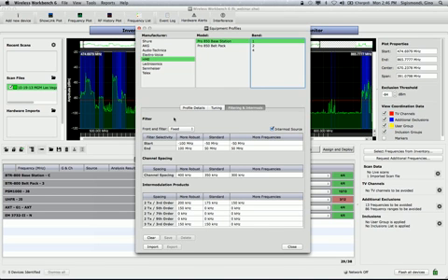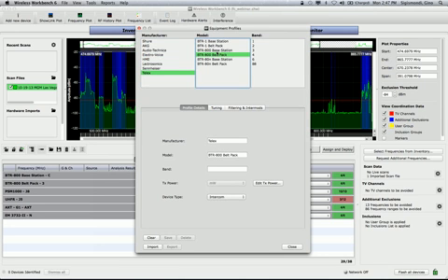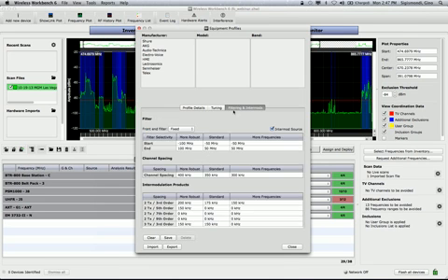And if I wanted to, I could either create a brand new one from scratch here, or I could select a particular one to branch off of, or Gino made his own. Let's see, if Gino wanted to make Gino's awesome wireless, what I could do is copy the parameters from that Telex system I selected, and now I've got all that data in terms of where it tunes and how it tunes copied in here, and I can tweak these parameters accordingly to correspond with whatever wireless system you might be using. And the manufacturer of the wireless system in question can probably provide a lot of this information. But the point is, this data specifies how much space each one of these frequencies needs.